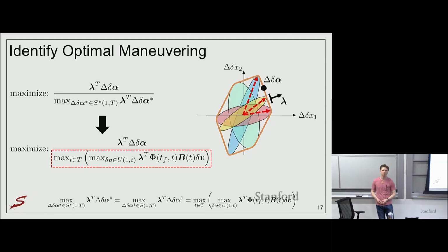What determines the length of your control window? You do. And in theory, if you were to adjust that, does that change the optimal? Yes, and that can be used in an actual real mission to get around difficult to solve or high cost reconfigurations. Say you wanted to do a large change in along-track separation. That's going to be really high cost over a very short control window, but if you just expand it, it drops significantly in cost, right? So it's a user defined parameter.